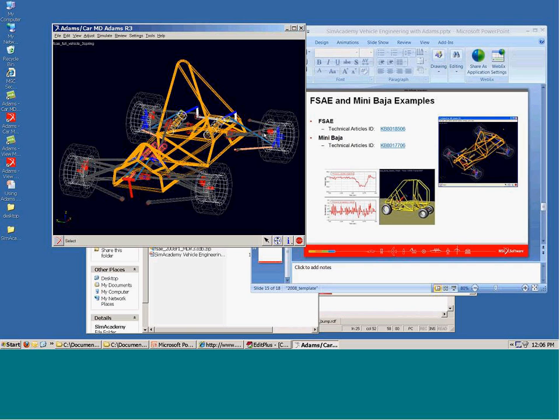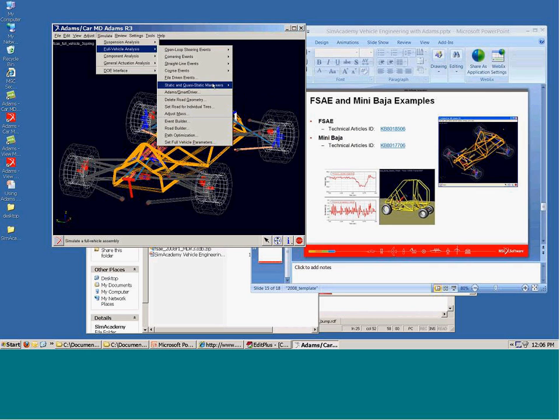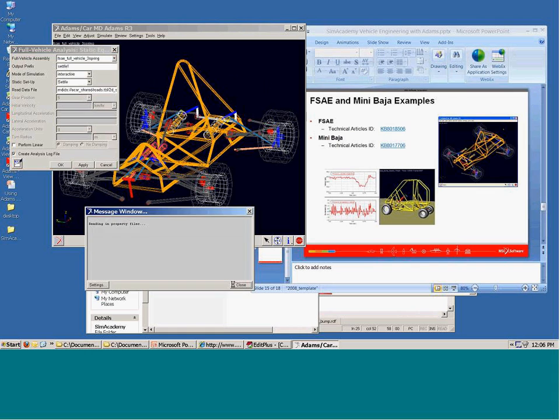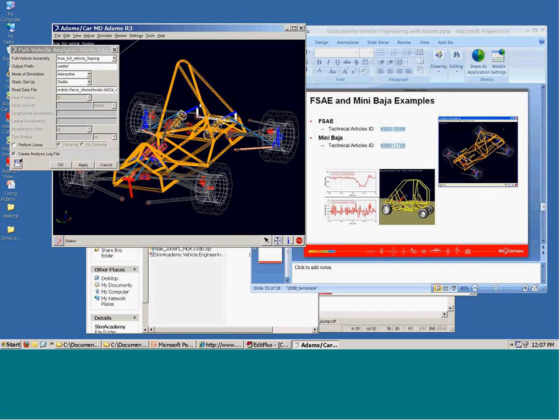Right? In addition, many times you may want to set up the vehicle. So say you just want to have the vehicle settled on the ground and look at spring preloads and ride heights, etc. So you also have an example here of, say, a static equilibrium where you just settle the vehicle. Now I come in, maybe change the spring preload.